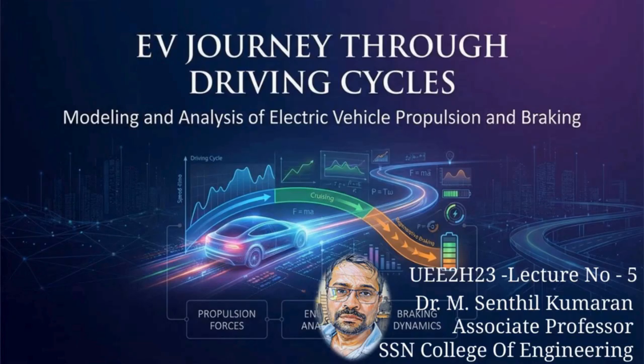The EV has a clear mission. First, it must predict how much energy it will use. The energy required depends on the forces acting on the vehicle, and the EV must overcome all these forces to move forward. Second, the EV must master propulsion. This determines how much power the motor must deliver at every moment of the driving cycle. Third, the EV must harvest energy while braking. When slowing down, energy can be recovered, and regenerative power equals regenerative efficiency multiplied by braking force multiplied by velocity.